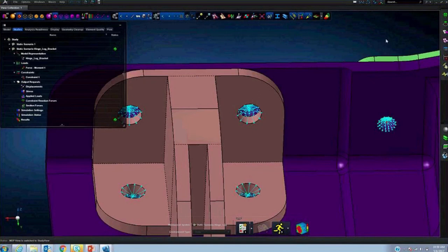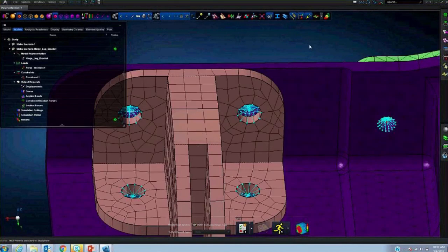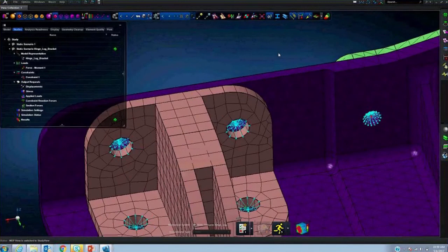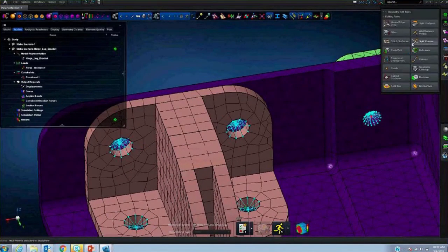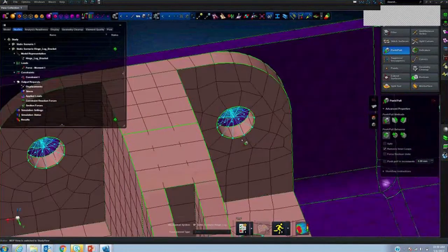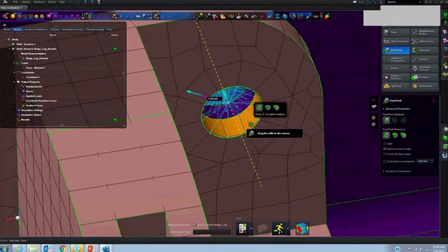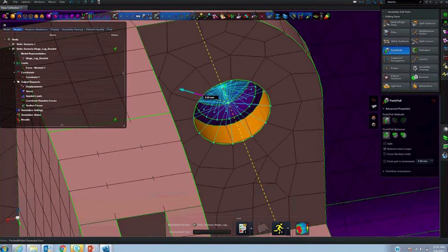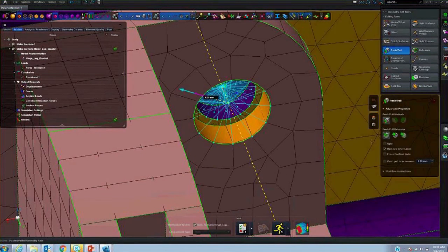For example, I would like to increase the diameter of that bolt, right? And what are the two things that one would do? I could go to the push-pull, in which I can select this bolt. Right now it is 3.18 radius. I'm going to make it as 4 millimeter. Now the diameter of this one increased.